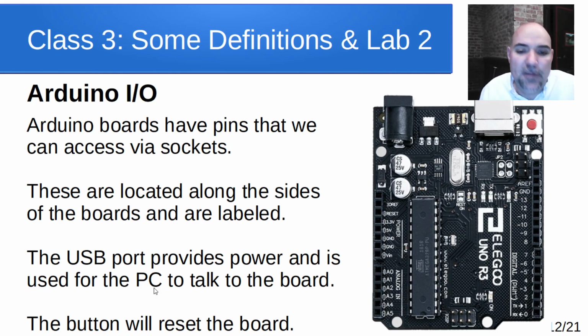All right, so the USB port is going to provide power. It's going to give us a way to program it. It's going to give us a way to also talk to it from the PC. And you'll also notice there's a reset button. So if you want to restart your program without doing it through the Arduino environment, you can just hit that reset button right there. When you let go of it, this will reboot this processor. And again, there is no operating system. There's no hard drive. The code is all stored on the microcontroller itself. As soon as you hit that reset button, it'll reset it and rerun the code back from the beginning again.